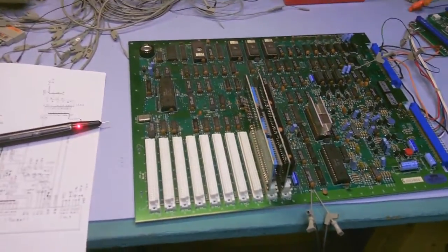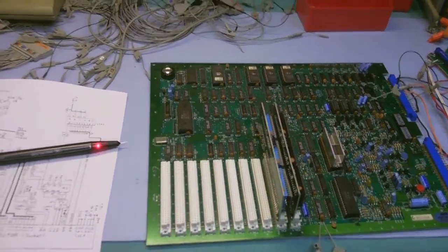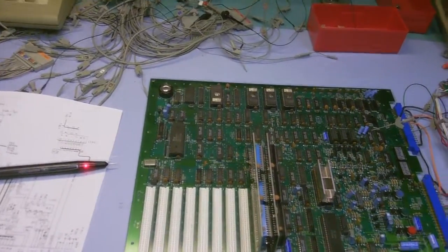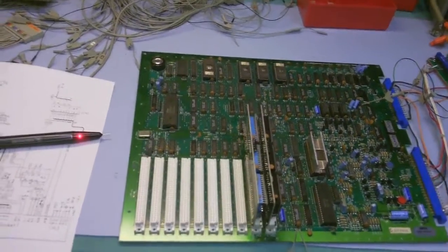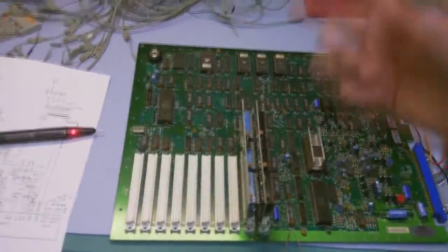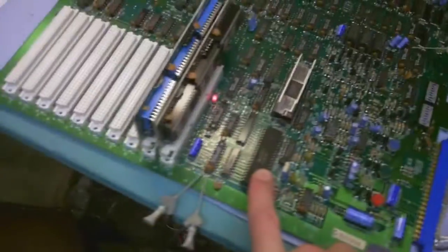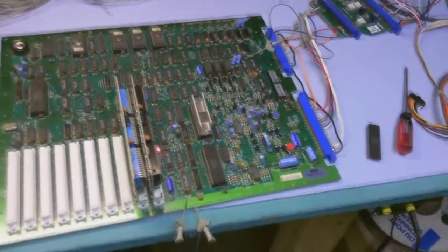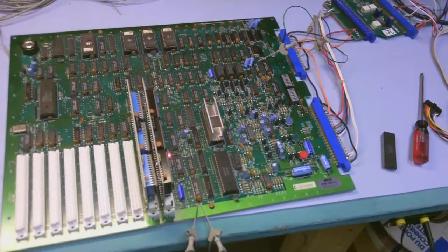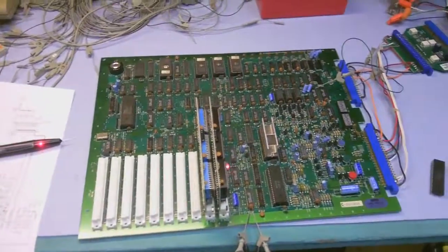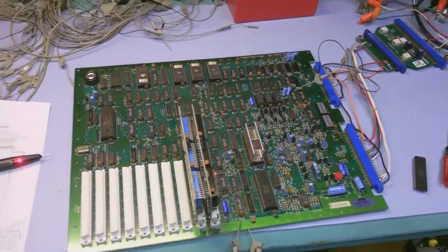So the way this works is there's several CPUs on here. One is the Z80, which drives the controls to everything else, and also it displays the menu to let you choose the game or whatever. When the player selects a game and then it decides to play, it turns control over to this guy, and this is the RP2A03. This is the generic chip that's in every classic NES, if you guys own an NES. That's the brains inside the NES. It's also the chip on, say, a Punch-Out that drives the music and that kind of stuff. And so it's very common with a lot of Nintendo games out there.